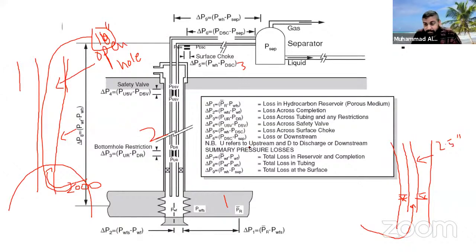So the well test, pressure buildup test, pressure drawdown test, those techniques tell you what the skin factor is. And skin factor, what is it? It is an evaluation of the permeability damage inside the hole. For example, if there's some plugging because of drilling fluid or something and your oil cannot flow, we call it a skin. So if a well has a high skin, let's say skin number 10, it means that well is very highly damaged.